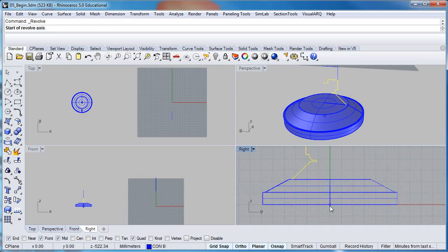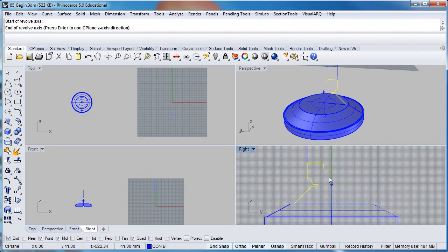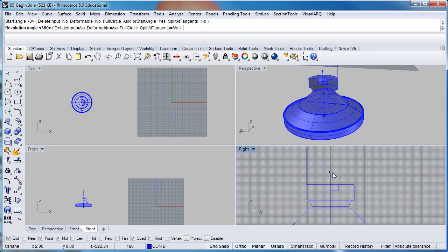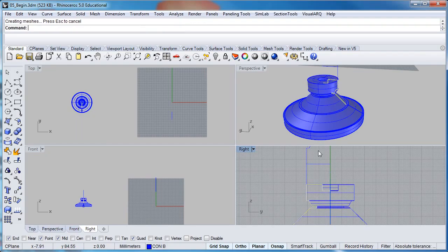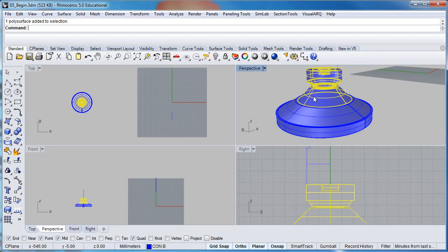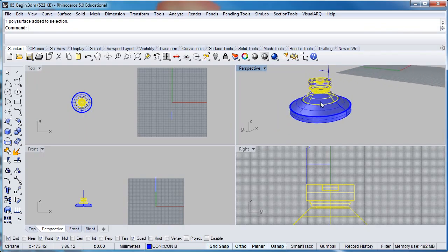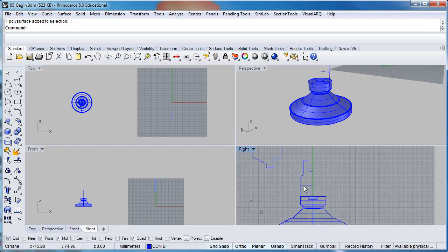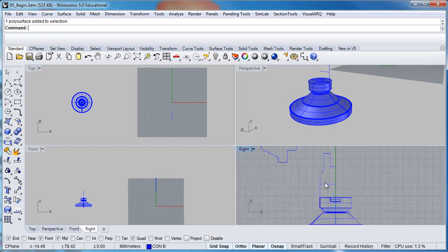We can click point, scroll up because ortho is already on, left click. It's asking for the start angle, right click. It's asking us for the end angle, and again we can now see that we've got the little supporting bracket that the foot is on. Last one as a repeat, so a lot of these skills, once you've got them once, you can get quicker and quicker with it, but we're going to do the top of the bracket this time.